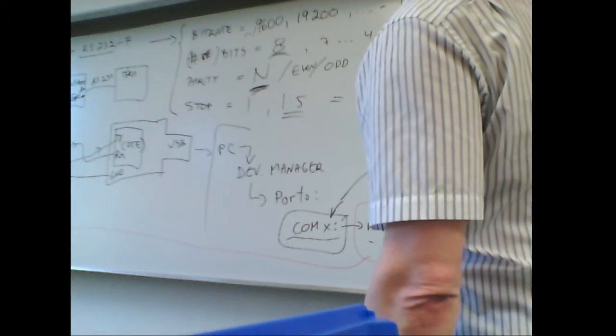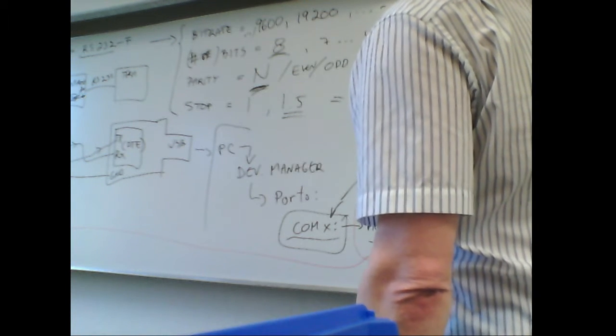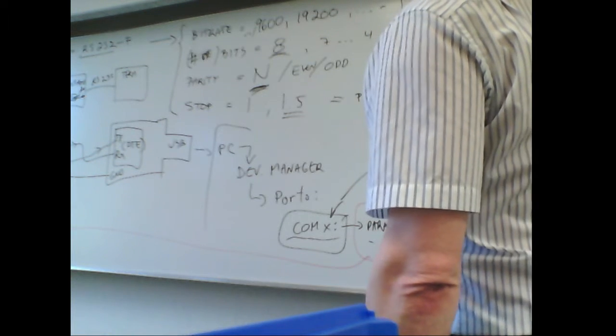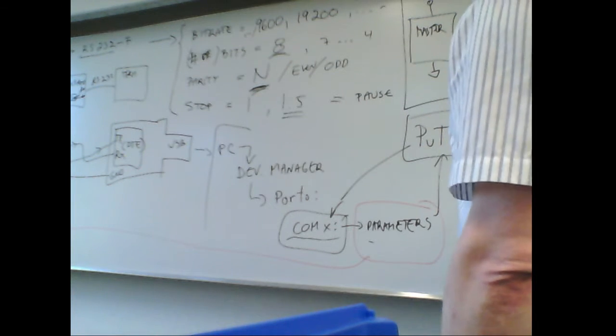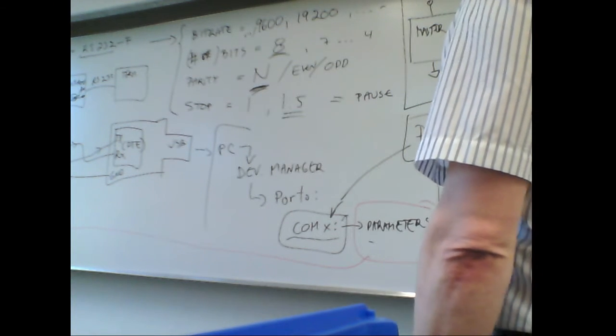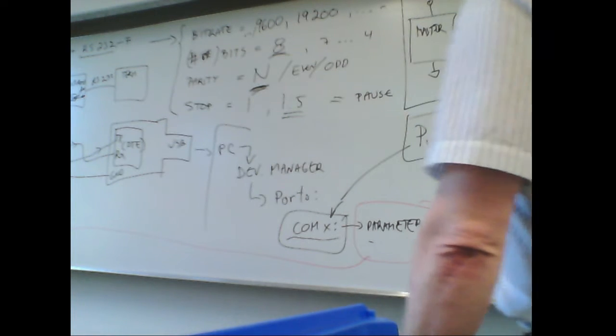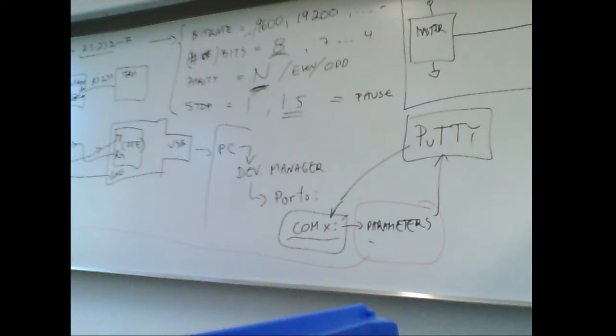Here we have the master device, which is powered normally. Then it has this Onewire line going to the device. Onewire means that you can actually power it up also from this line directly. You do not necessarily need to power this one from any external power supply. But since that is available, why not use it?